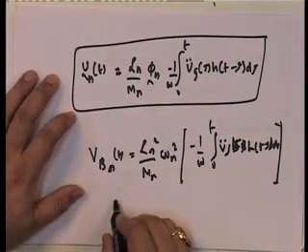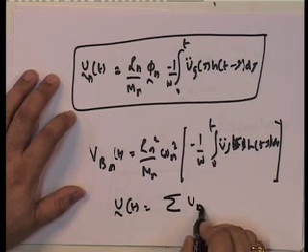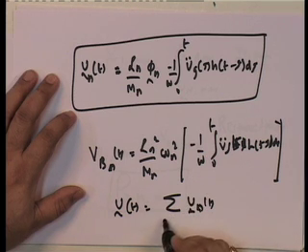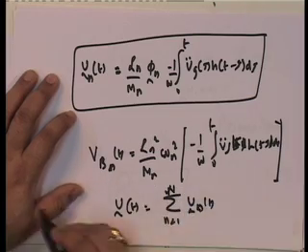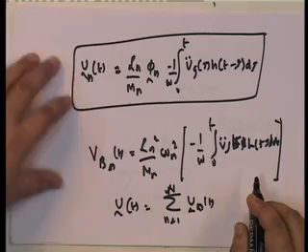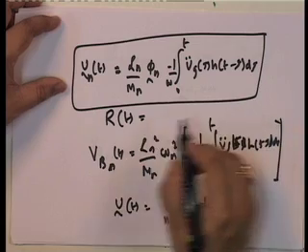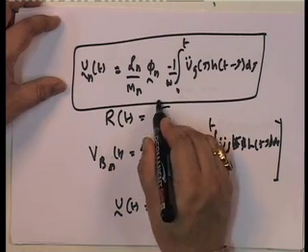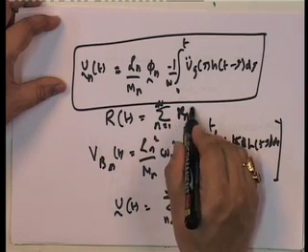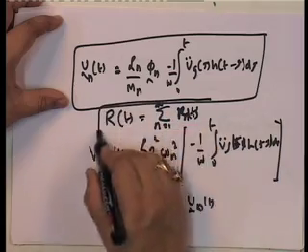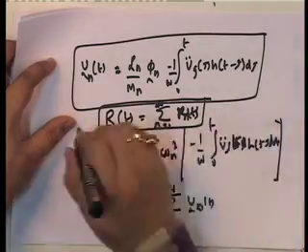So V of t becomes just the summation of Vn of t, n going from 1 to N. Similarly, any response quantity, if I had the time history, would be equal to the summation n going from 1 to N of Rn of t. Note that this is valid. Why? Because at any instant of time, I can always add them up.